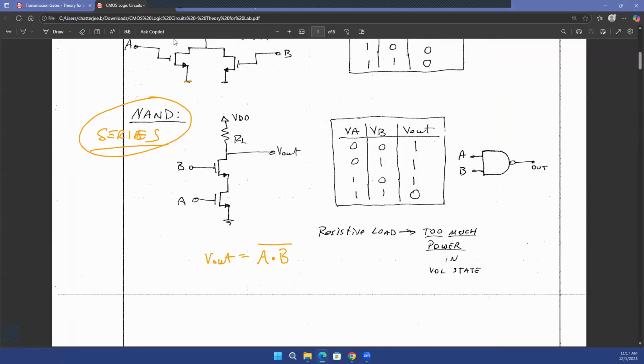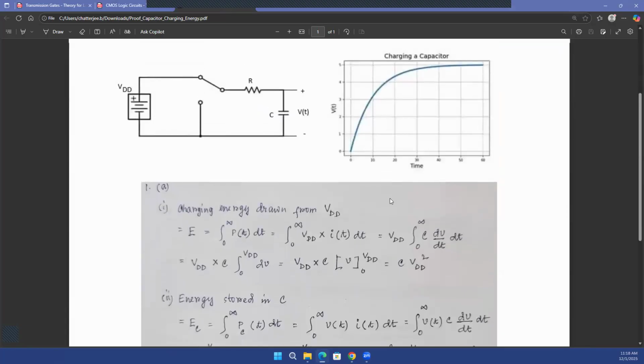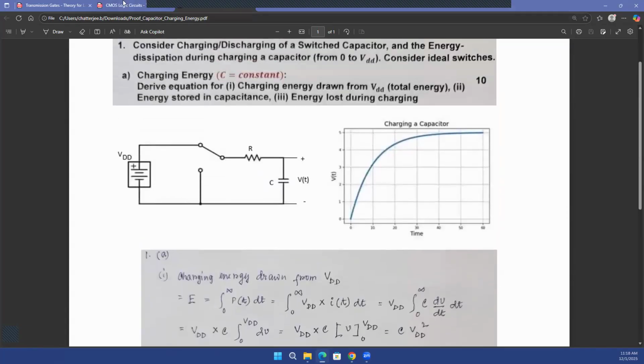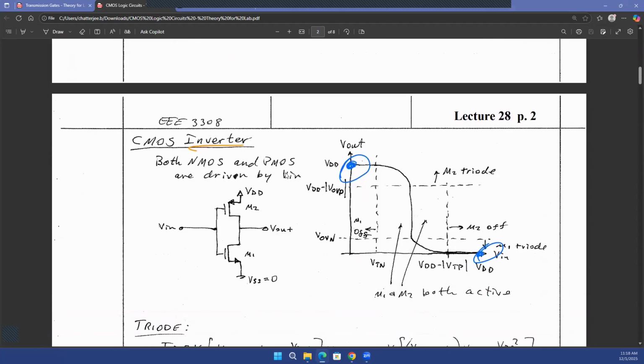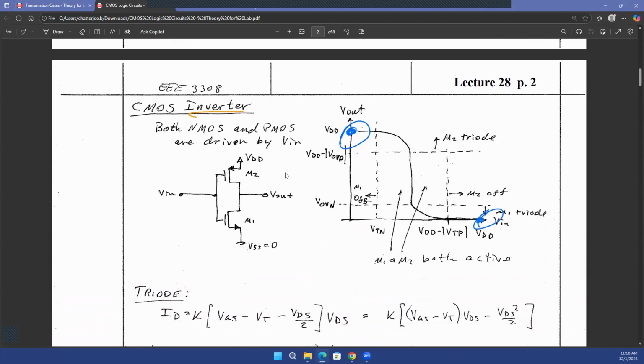All right. So we know that switching will result in some amount of energy being lost. However, the good thing is the energy is lost in digital circuits only if it is switching. If the inputs are not switching, you don't lose any energy, because the capacitor is storing the charge and it will keep on storing the charge.